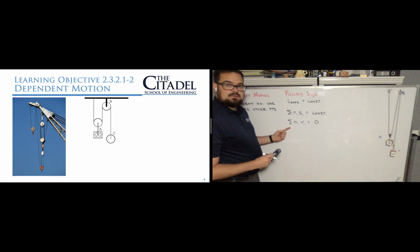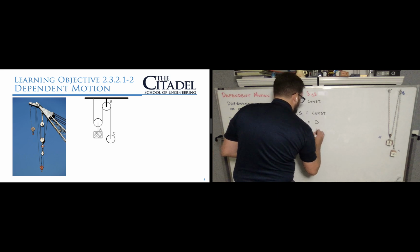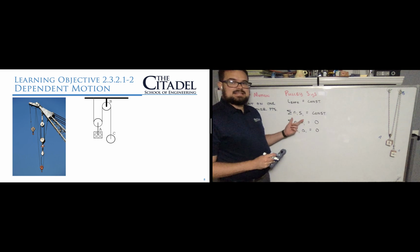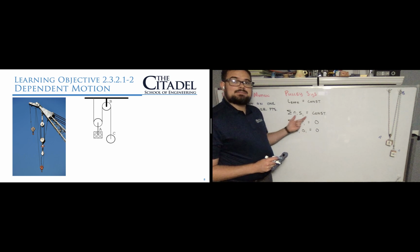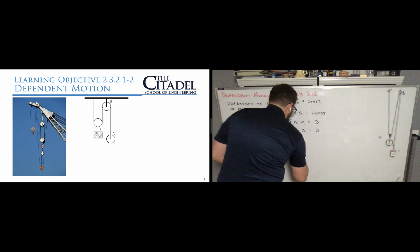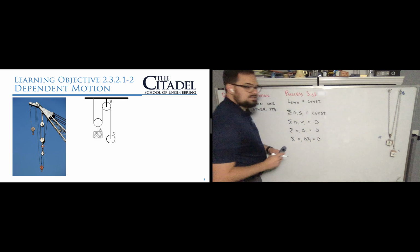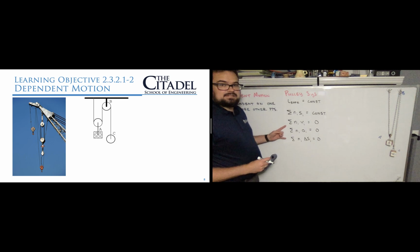If we take the derivative a second time, we're going to get acceleration. Now, the other thing to recognize is that this constant means that for any given point, this sum of n times s_i is going to be the same. So if we set them equal to each other and take the difference between the positions, we would also see that's equal to 0. So the sum of delta s for each individual point is equal to 0. And it turns out that these are our dependent motion equations for pulleys.